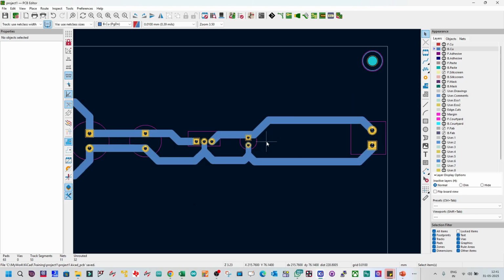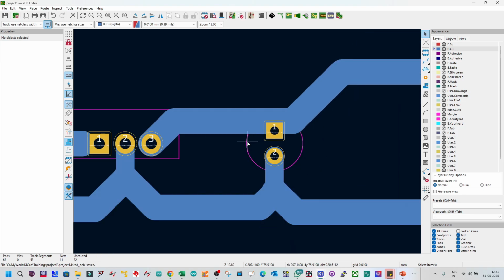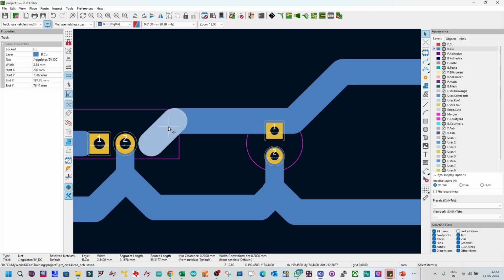And if you put a full load condition, and your regulator is not placed properly, maybe it will not do decoupling and filtering in an efficient way. So it should not take output from here and put a very big loop inductance into the capacitor leads. That will be a problem. Okay, let us not go into that technical part. Let's complete this.